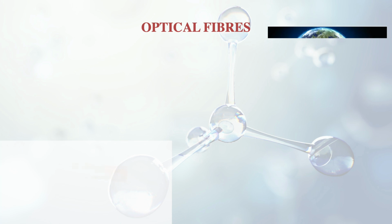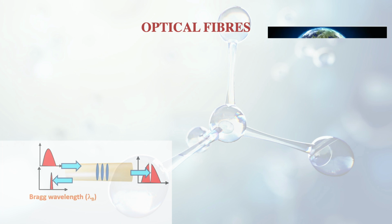So FBG is a set of gratings which are imprinted in a small segment of the optical fiber such that they reflect a particular wavelength of light and allow transmission of the rest. So if a wide band of light is passed through the fiber, we'll find that most of the components are transmitted through the fiber, but one particular wavelength, which is called the Bragg wavelength, is reflected back.